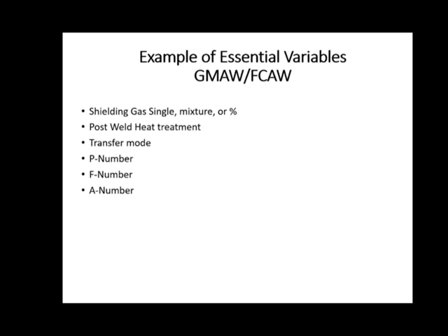that supports your change. So for shielding gas, if we went from a single constituent gas like pure argon to maybe a mixture that was 75% argon, 25% CO2, we have to requalify. We need to do another PQR that supports that, hey, we changed this gas and we can deposit sound weld metal into the weld joint utilizing this mixture, which is different from our original.